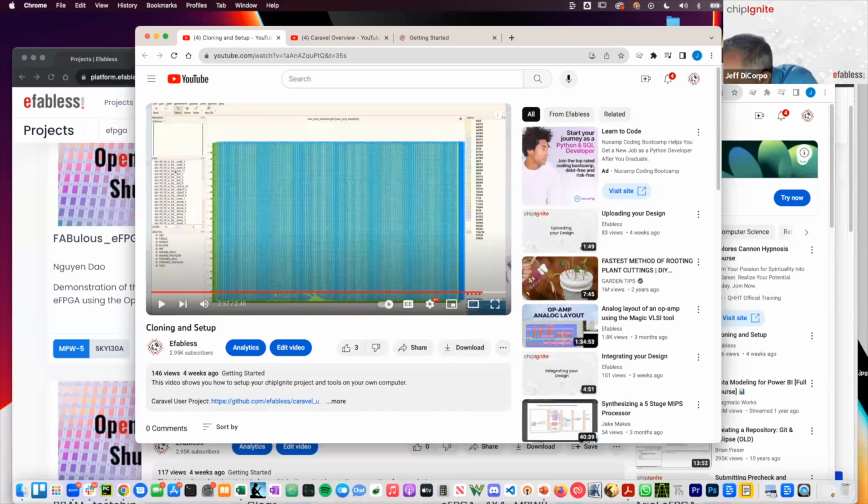Okay, max frequency of Wishbone we can run on Caravel, 40 megahertz. Does 40 megahertz work? Yes. Well, do you want to talk to that, Andy? Yes is the answer. So basically, yes. The default core clock frequency that we have on our development board is 10 megahertz. But there's a clock system that you can modify, including increasing it through a PLL. That's within Caravel.